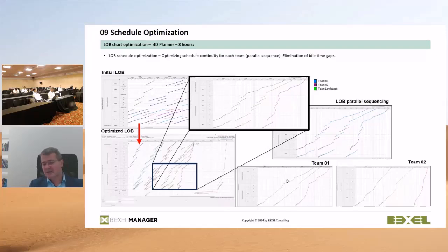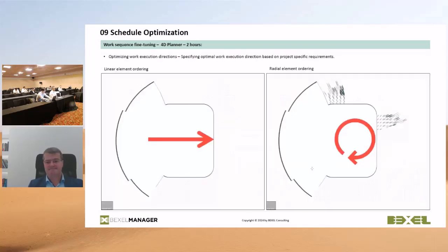Another interesting thing is that Excel, by this leveling of resources, automatically calculates, by knowing the quantities in each zone and subzone, that sometimes the optimal plan looks like this. It does not need to be a straight line, because in a certain zone you have more concrete works or more metal works, and Excel adjusts this so in reality flow lines look like this.